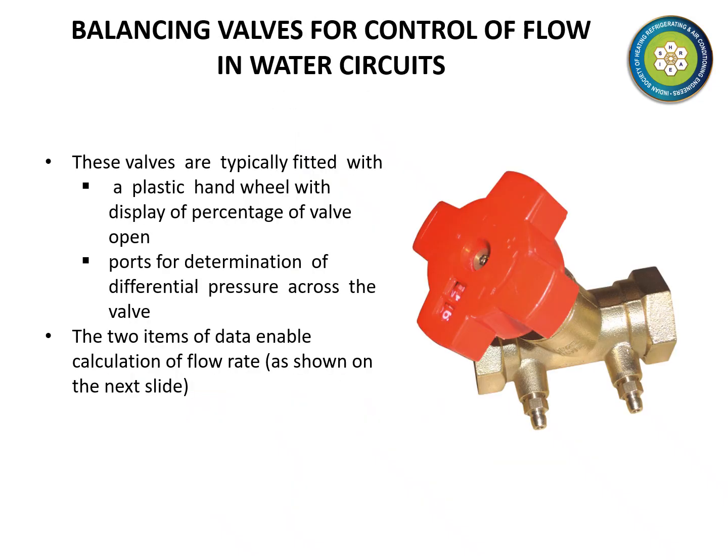Very good flow control is possible using balancing valves. These valves are typically fitted with a plastic hand wheel with display of percentage of valve open, as well as ports for determination of differential pressure across the valve. These two items of data enable calculation of the flow rate as shown on the next slide.